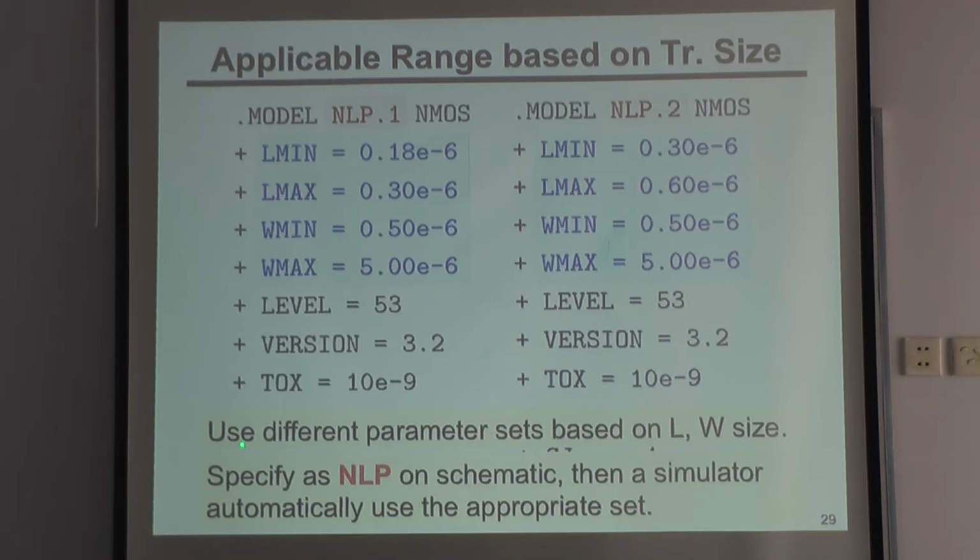In other words, we use different parameter sets based on L and W size. But on the schematics, we don't have to put NLP.1 or NLP.2. We just say NLP is okay, and the SPICE simulator automatically uses the right set based on L and W.